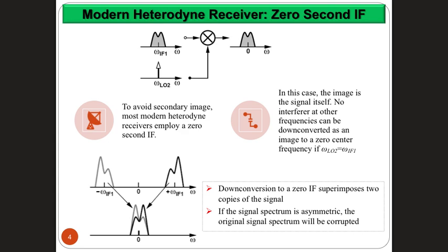which is that the signal itself becomes the image of itself when you are trying to demodulate. Okay? When you studied your communication course, we did not really discuss this that much, because in all those communication course diagrams, this positive side of the signal and negative side of the signal they looked exactly the same. Why? Because the signal itself was a symmetric signal around its center frequency. So in your communication course, the signal always looked something like this. Very nice, symmetric. Positive side looks exactly like the negative side.